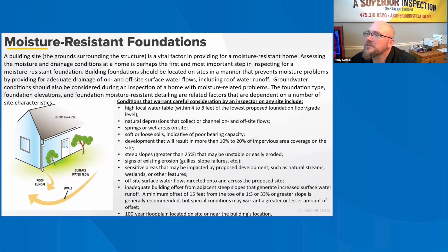Actually, let's see here. Just an FYI on window installations. Check the installation instructions, as many manufacturers use different ways they want the windows installed, i.e. Andersen and Marvin are different. Agreed. So Michael makes a good point.